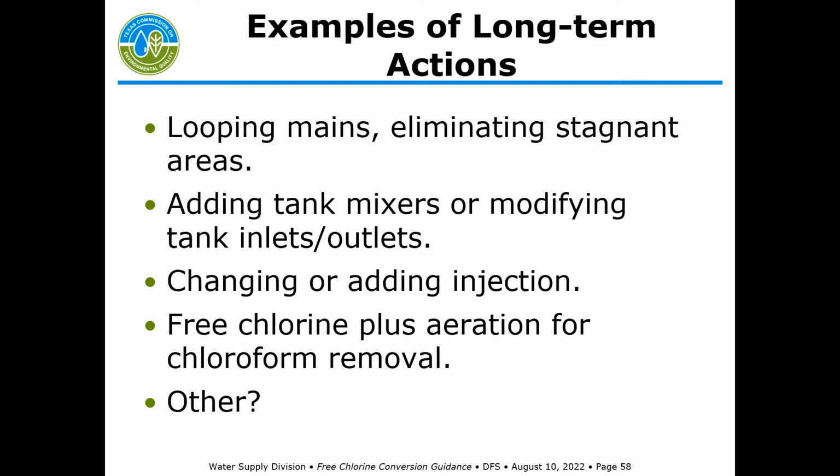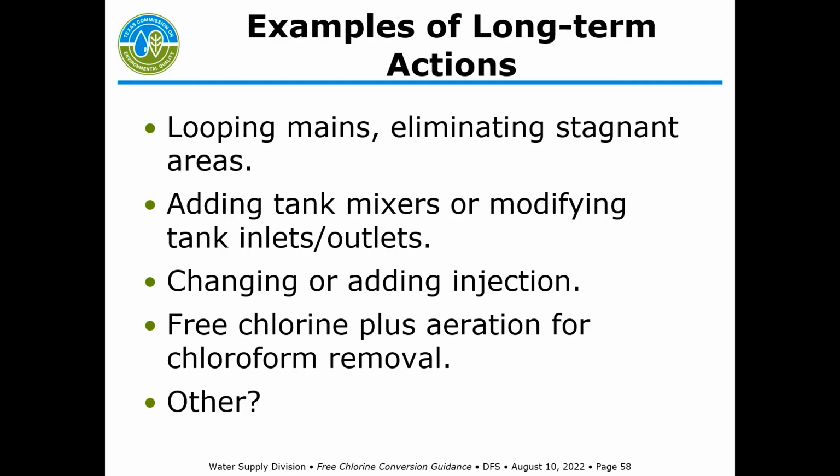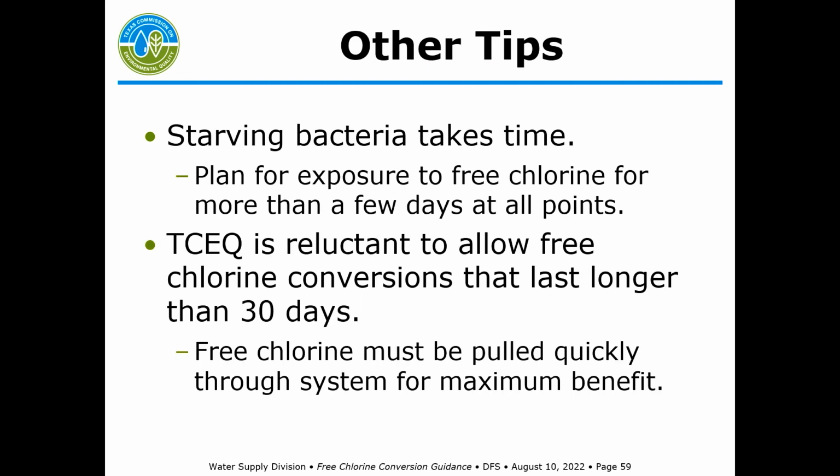This next one is, if you're in the situation where we just can't make monochloramine work, and we're going to switch back to free chlorine under normal conditions, well, you've got to deal somehow with the trihalomethanes and haloacetic acids. So could aeration help you at that point? Maybe. And are there other things? Absolutely, that might work, but it would have to be something you work out, typically with your engineer.